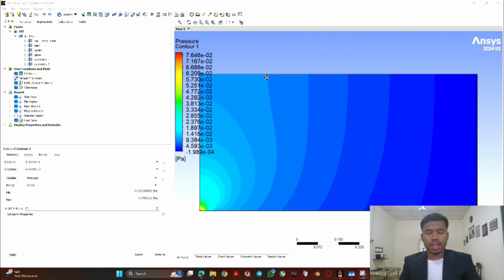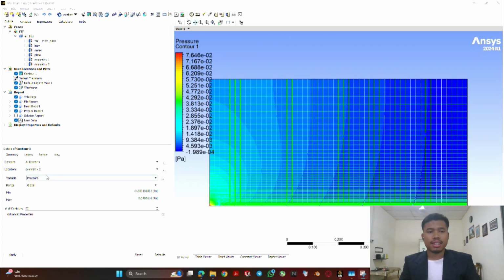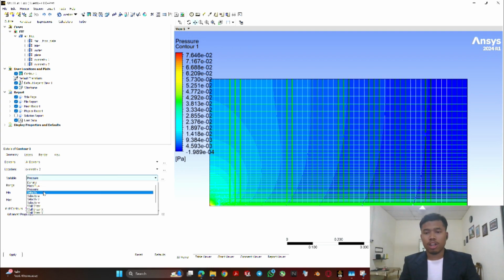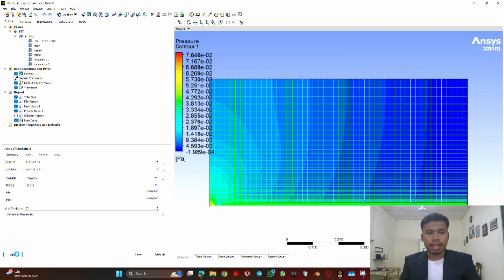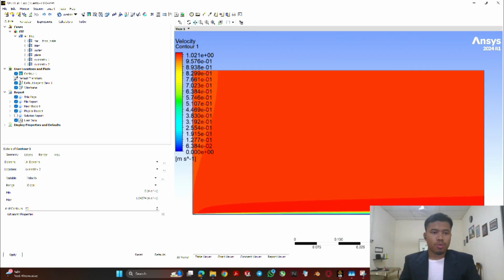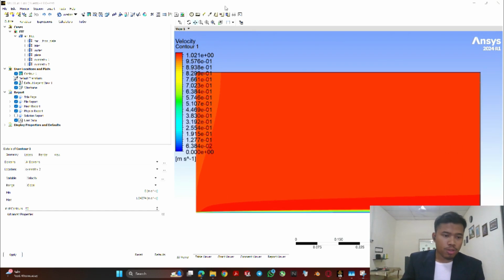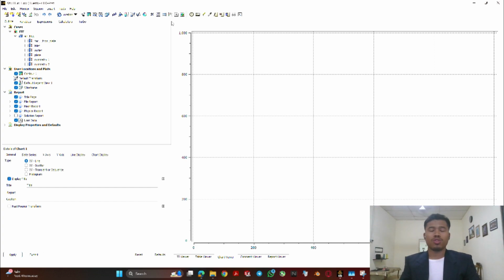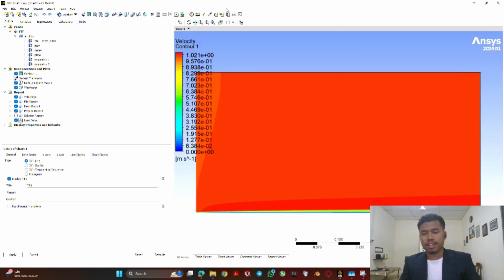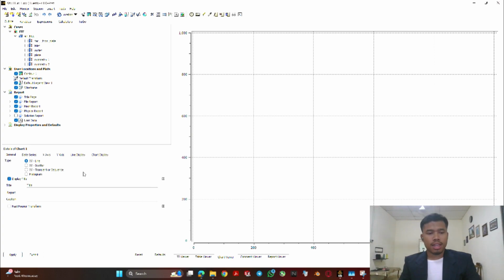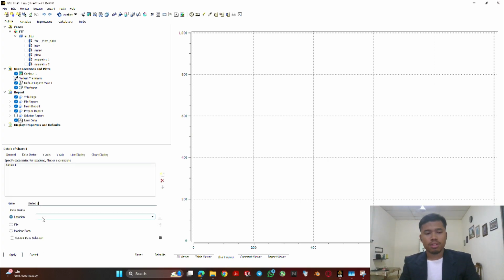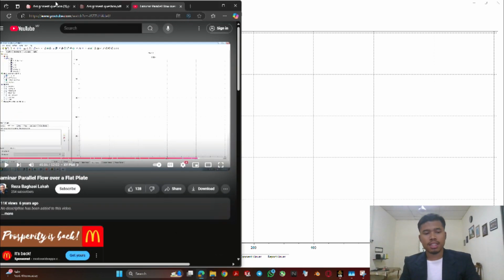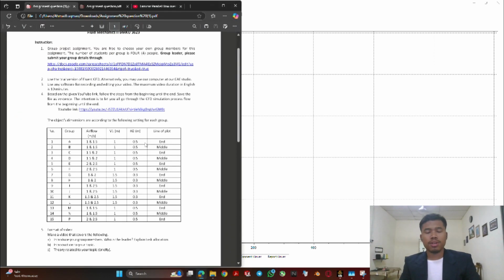Now, before we start on XY graph, we must select the line by clicking on the locations and select the line. We go to the option which goes to point 1 and point 2. The point we use is where we want to calculate, which is at the end of the flow. And then there's the location I put as the mark, and then there are samples. For now, we can use many things, but we will use the 35 samples for now.